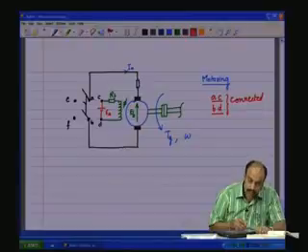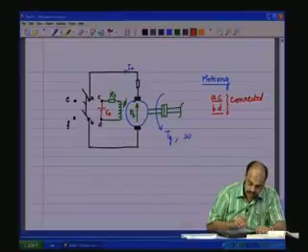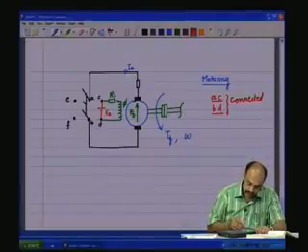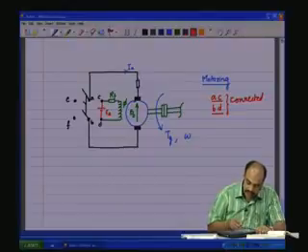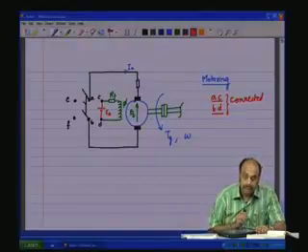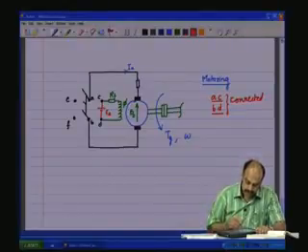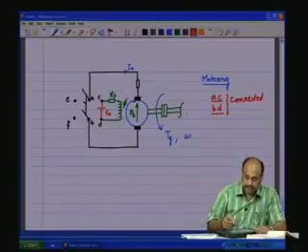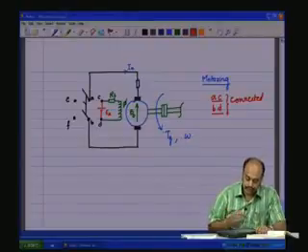That is, here we put this double pole, double throw switch to positions C and D. So, the armature voltage is applied to the brushes of the motor. So, this will cause IA to flow and therefore, motoring will happen and then there will be generated torque and therefore, the speed.